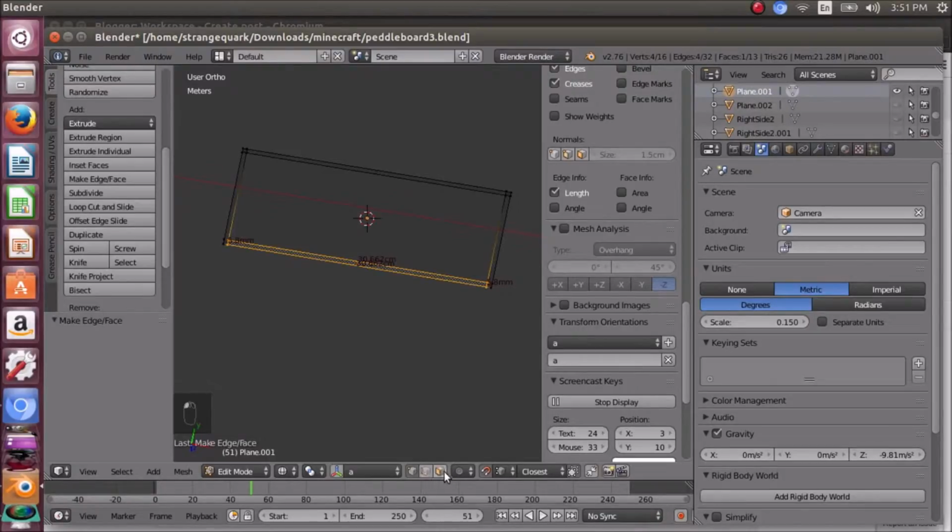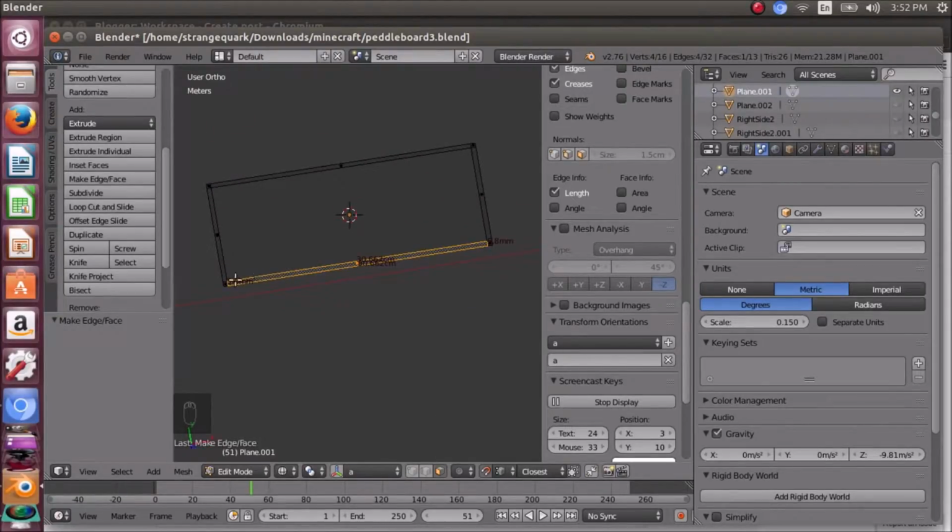If we toggle with right mouse button click, when you have overlapping faces for a given area, you can double toggle, or in some cases triple, depending on how many faces are overlapped in a given region. The new face that we constructed for this region, which is delineated by these 4 vertices that are shown, is the new face. We don't want to delete that, so if we toggle the right mouse button again, it'll select the old face that we do want to get rid of.